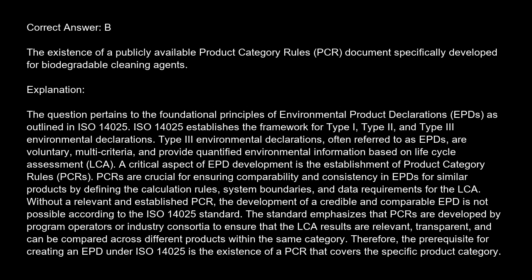ISO 14025 establishes the framework for Type I, Type II, and Type III environmental declarations. Type III environmental declarations, often referred to as EPDs, are voluntary, multi-criteria, and provide quantified environmental information based on life cycle assessment, LCA. A critical aspect of EPD development is the establishment of product category rules, PCR.